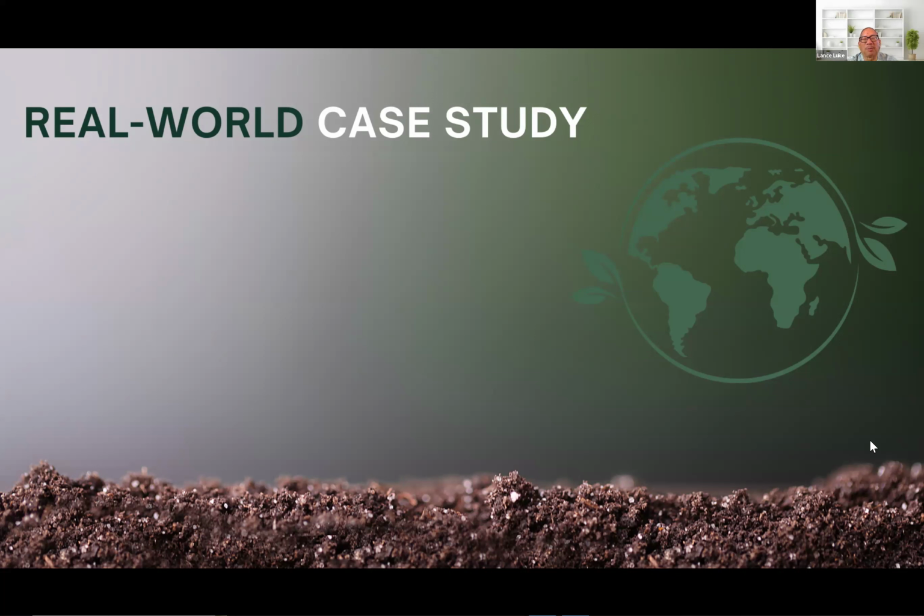Well, not all of it, but maybe up to 4 feet or so, the area that was sinking. Then we had to bring in new soil called engineered fill that could be properly compacted. And then we used a geogrid system and new asphalt. And that seemed to do the trick. So that was a situation where we missed getting test results early on, and the remedial fix was costly.